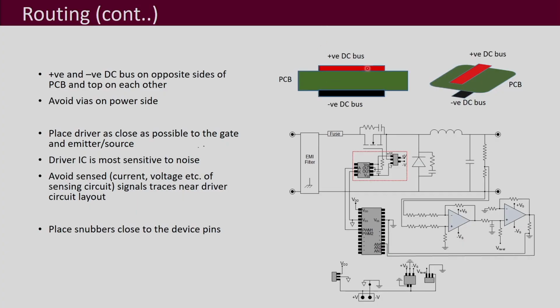that let us say we have a DC bus, a positive DC bus and a negative DC bus. Now, we know that there is a stray capacitance here, but that stray capacitance is not undesirable. If we place a positive DC bus and negative DC bus on top of each other like this, that C is beneficial over there. So, this is sometimes done. Your positive DC bus and negative DC bus are laid out one on top of each other.